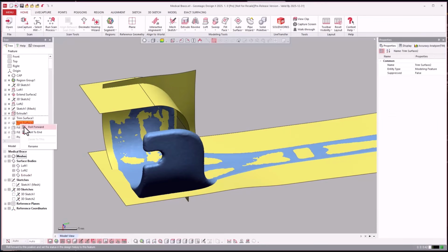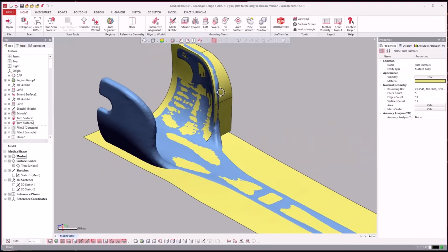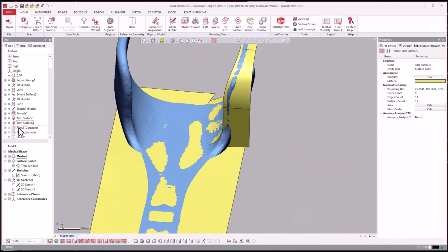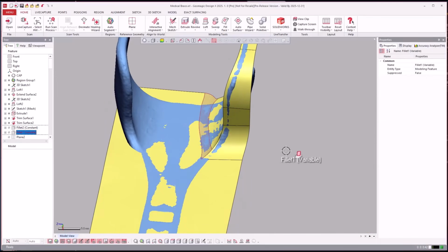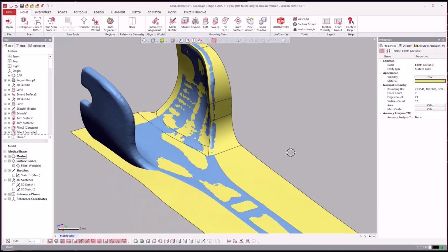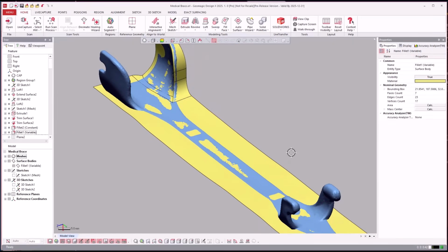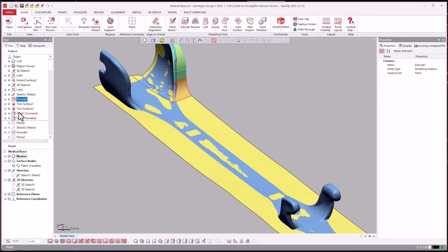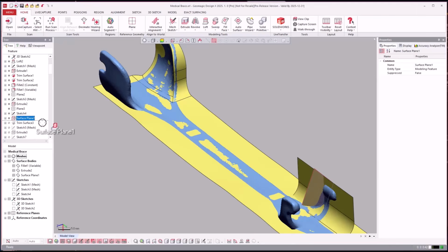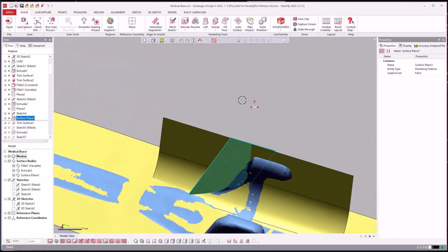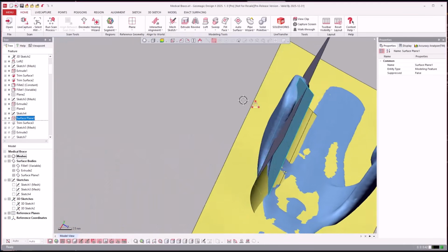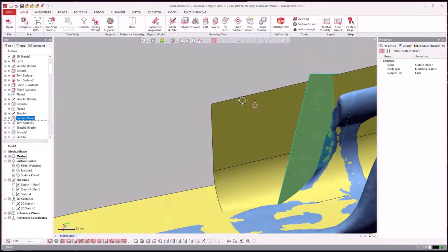And then we're going to trim all that together. Very little fillet cleanup there. Looks good so far. And then the other thing is modeling half of it and mirroring it across is obviously what's going to happen too. Now we went ahead and did an extrude surface there.